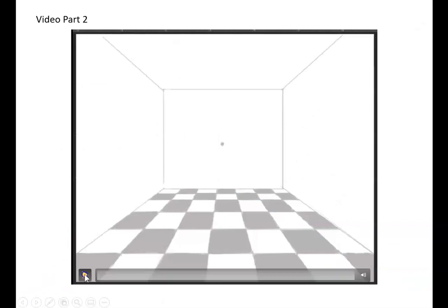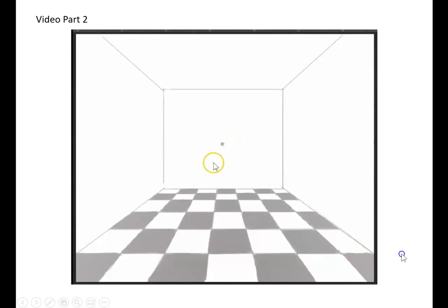Now my second video, as you can see here, I already shaded all these lines. Here I erased my 8 lines, but I kept my vanishing point. Keeping the vanishing point is very important. What I put here on the back may be a window. Let's consider it a window. My goal now is to draw a window on the side of the room. So how do I make sure that this window on the side of the room would be the same height as the window that we see now?